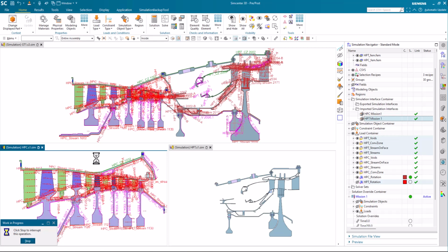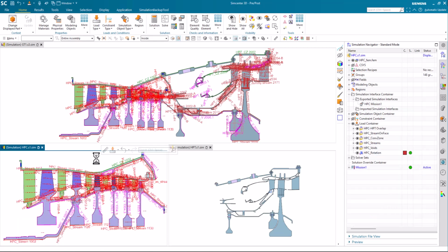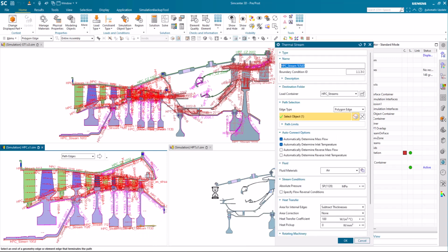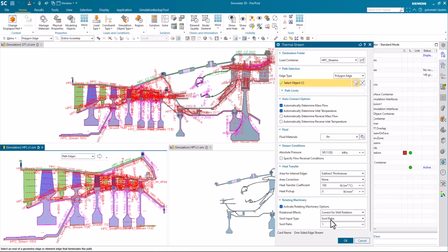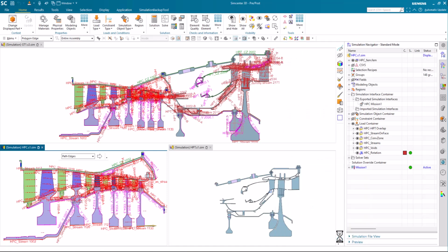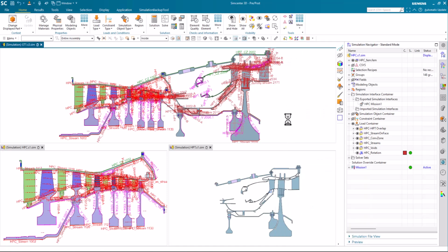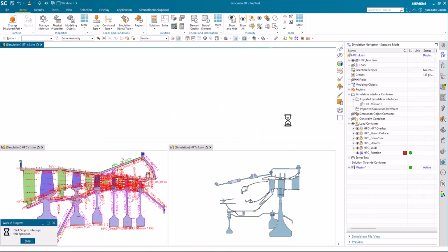So we switch into the compressor simulation, and we're going to modify the stream 1130 on that last dip. We're going to change the swirl input type from being defined with a ratio to that of a velocity, and you see our expression based on radius and NH, a condition parameter. So I say OK to that, and then go back up into the assembly's simulation.